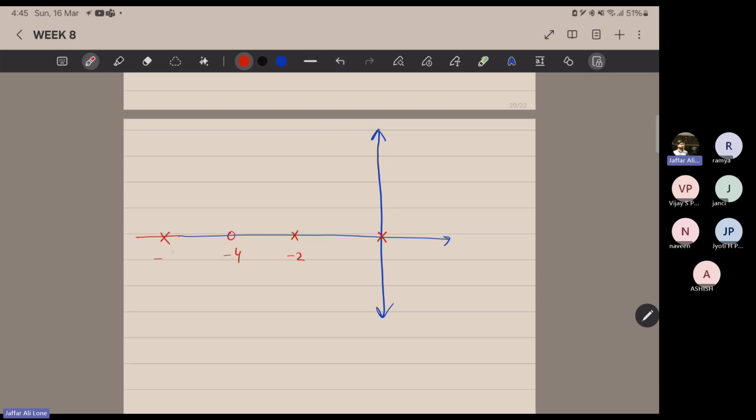We have a pole at -8. Now, which part is the root locus? This region is a part of root locus. Similarly, this region is a part of root locus. So root locus will start here and terminate at this zero, which is at -4. Then there will be some breakaway point. This breakaway point is here, and my desired pole is here. So what will happen?